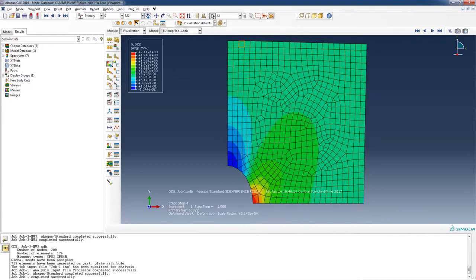And because of the way I set up this mesh, we talked about this in class as well, the load that's applied on the top edge gives me a nominal stress of 1 megapascal down on the bottom. So this number right here represents the highest stress in my mesh at the most highly stressed node, and it happens to be 2.117.